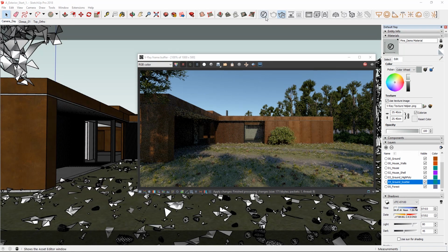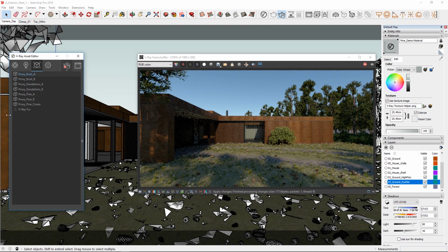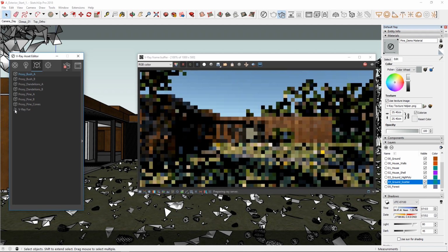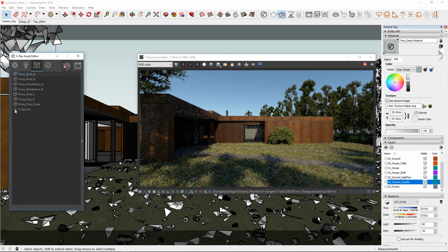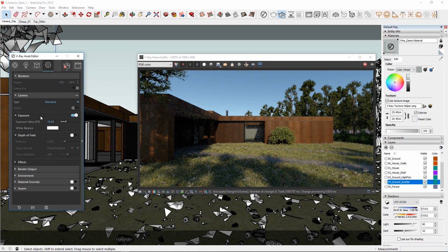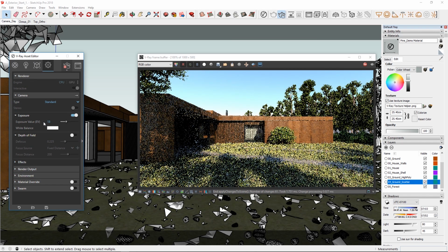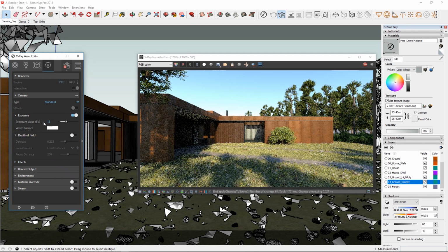Okay, I'll switch back on the grass to see how the image looks. I think now it's a bit too dark, so I'll adjust the camera's exposure value to 13. And instead of the clear sky, I want to have clouds, so I'll replace the sky with an HDRI.